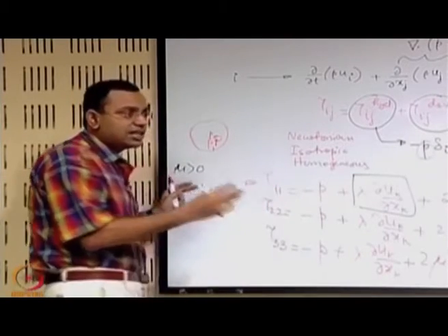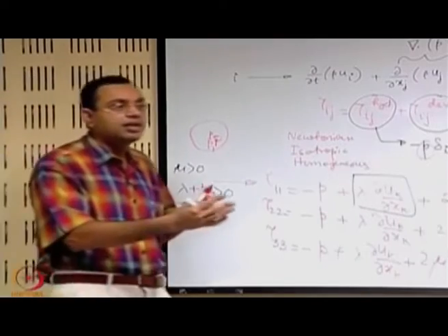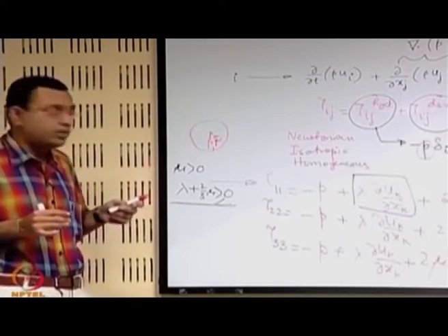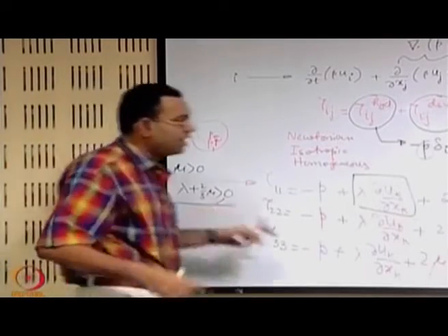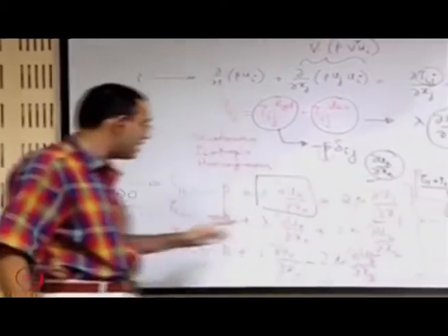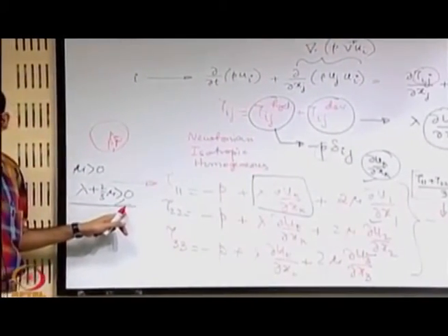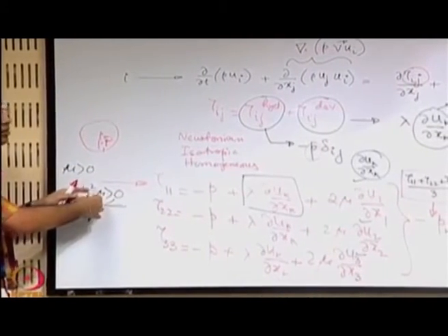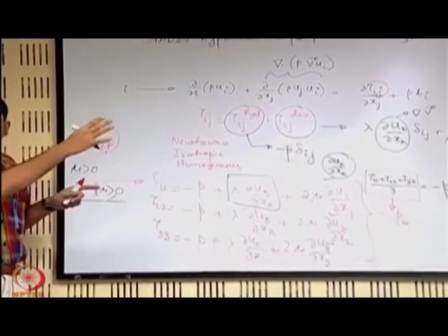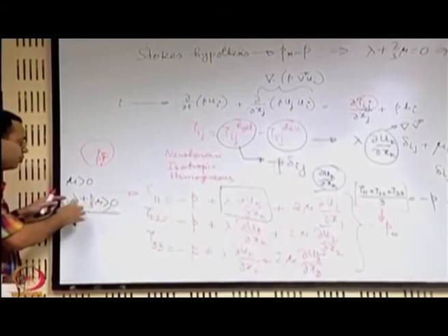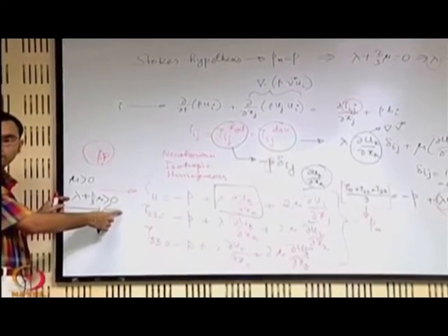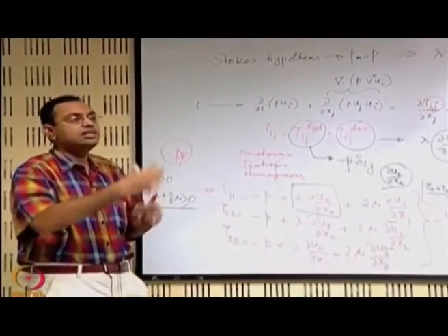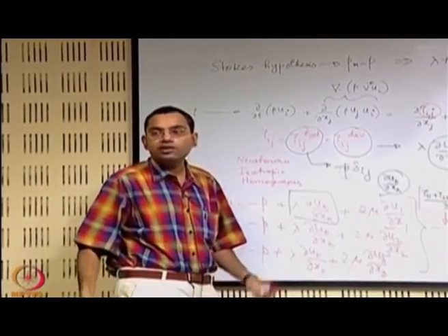See, that is where there will be a difference between doing abstract mathematics and the physical reality. When we are talking about abstract mathematics and if you are devoid of the second law of thermodynamics, you do not care. Up to this point no derivation has really restricted that this should be greater than or equal to 0. You could use any value, say you may say that well I will use a positive mu. Till now we have discussed that you should have a negative lambda, but with many combinations of positive mu and negative lambda this may not be satisfied, but we have to satisfy this, otherwise it will violate the spontaneous change in a natural process that should be according to the second law of thermodynamics.